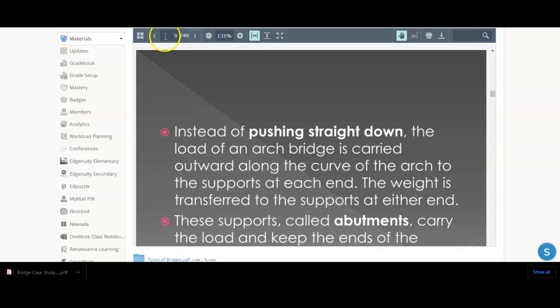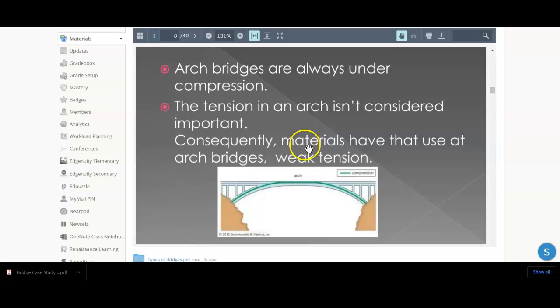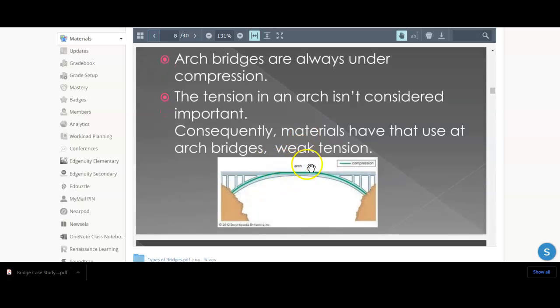And so the arc on the bridge is always under compression. You can imagine if there was a truck right here, this deck would want to bend down because of the amount of weight, but due to the arch in place, in engineering, the idea is to transfer the weight evenly throughout all the material, so that not one piece of material, not one cross beam, is experiencing the entire load of whatever's on top of the bridge, because that's how failures happen.